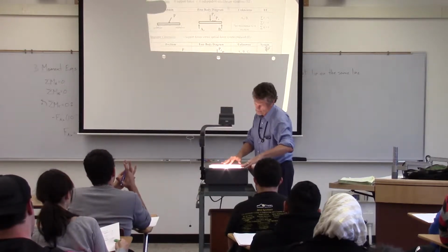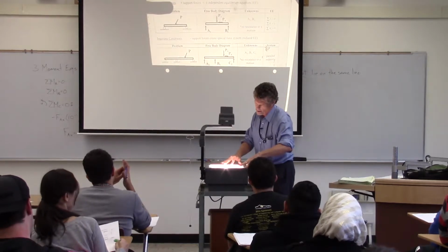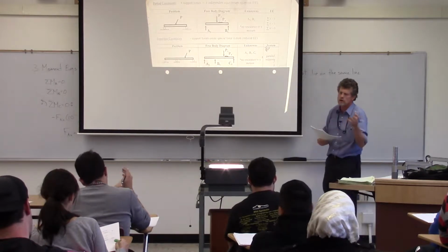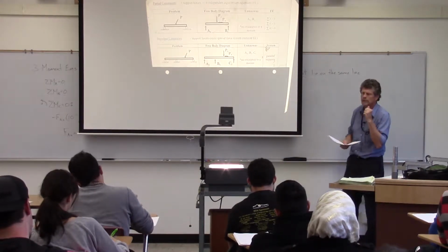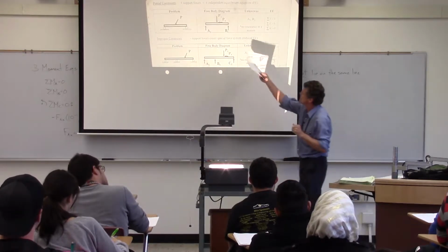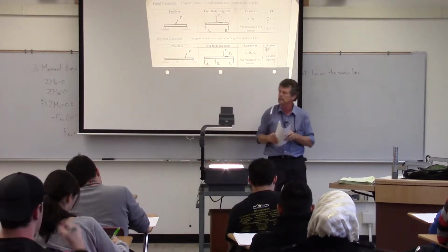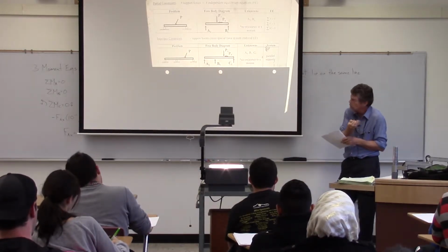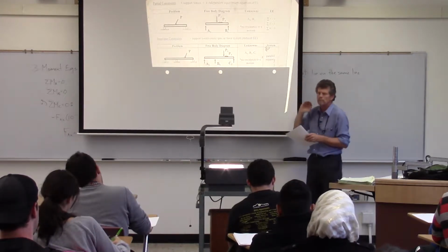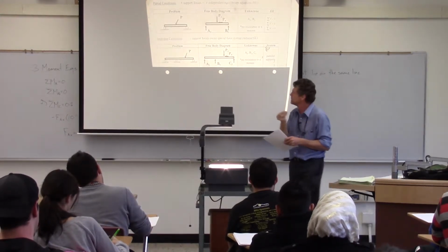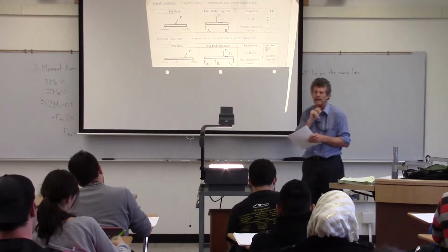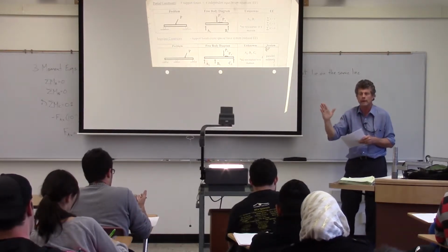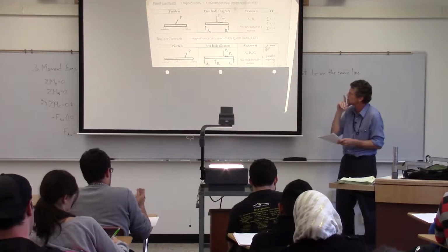The next one we'll look at is what we'll call improper constraints. So that means there's enough unknowns there in terms of the supports, but they're not really situated properly. And this is a similar problem. We just add another roller to that. So what we find is that I've got 3 unknowns there and 3 equations of equilibrium, but the problem is that they're parallel. And again, I have that problem where I don't have the ability to resist anything in that x direction. So I have enough unknowns, but unfortunately, my unknowns are situated to, again, that special equilibrium case that we were talking about there.